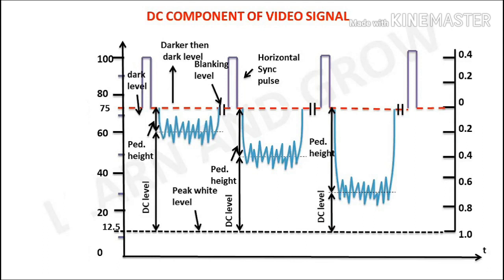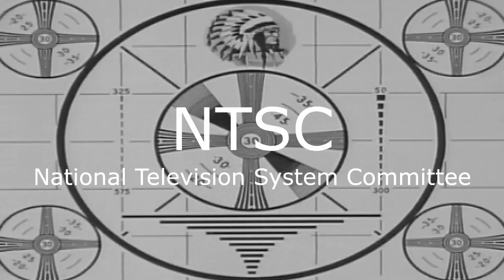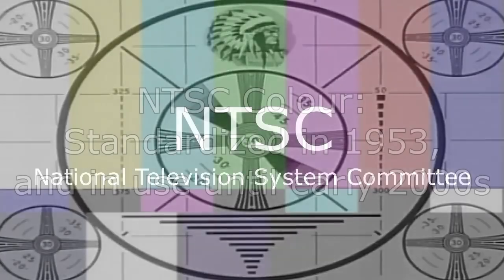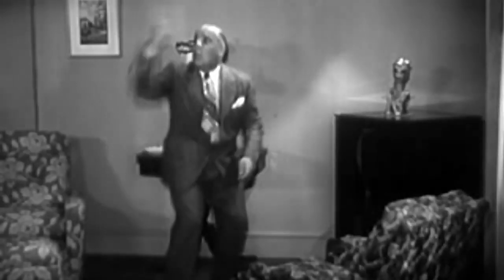If we assume that the vertical flyback begins with the leading edge of the third serration, then the time of one line elapses during vertical alignment before the flyback begins. Also, 6 pulses to equalize the same 3 lines occur before vertical alignment. So 3 plus 1 equals 4 lines are left blank at the bottom of the image, just before the repetition of the vertical trace begins.